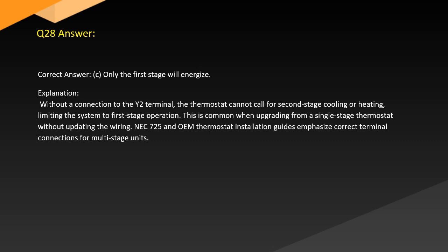Answer. Correct answer: C. Only the first stage will energize. Explanation. Without a connection to the Y2 terminal, the thermostat cannot call for second stage cooling or heating, limiting the system to first stage operation. This is common when upgrading from a single stage thermostat without updating the wiring. NEC 725 and OEM thermostat installation guides emphasize correct terminal connections for multi-stage units.